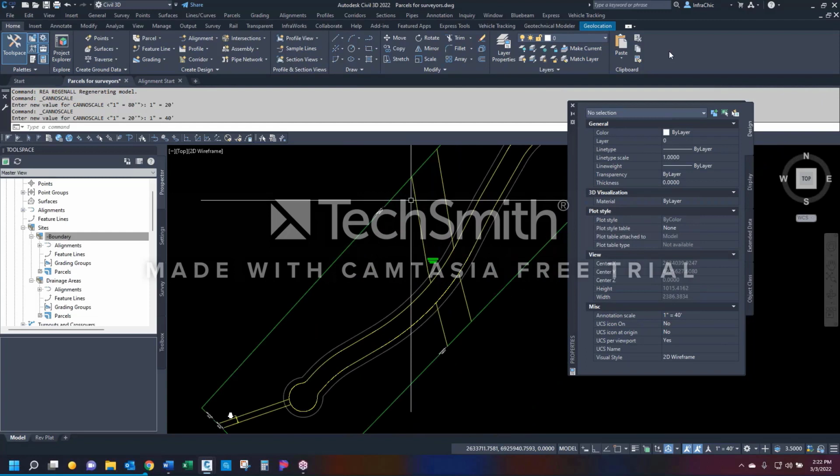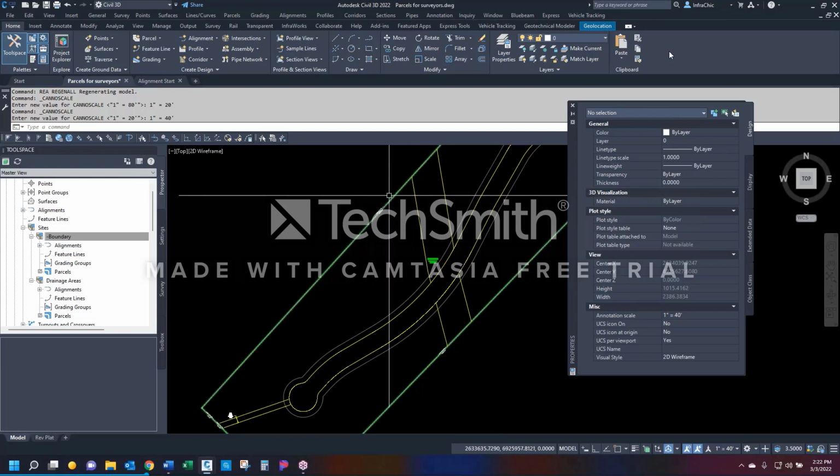So the idea is it's layer manager controlled at this point, which means when I XREF this into another file as an existing file, I can control how that layer looks. I can control, does this now bold in my proposed file, or is it screened back? Is it supposed to be Phantom 2 or hidden? What line type should it be? I can now control that in my XREF because of that.